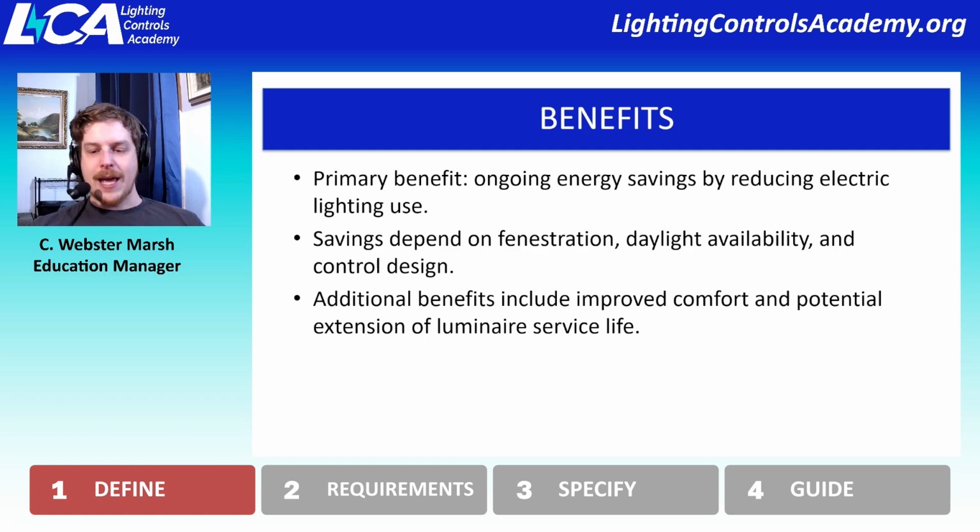Adding electric lighting to daylight might actually make it too bright of an experience in some cases, so you want to make sure that people are comfortable in the space when there's daylight present. The other thing is that the less we use our fixtures at a high intensity value versus a low intensity value, if we dim fixtures down a lot, we're actually going to save the lifespan of that, because most fixtures nowadays are LEDs, and LEDs wear down with use.